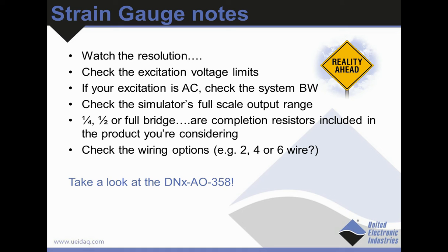can support it. Almost all strain gauges are measured in bridge configuration, so make sure that you're either purchasing a simulator that has the bridge completion resistors, or that you're prepared to add them yourself. And also check the wiring options, because there's 2, 4, and 6 wire connections. I won't go into details, but obviously we do have a strain gauge simulator board too.